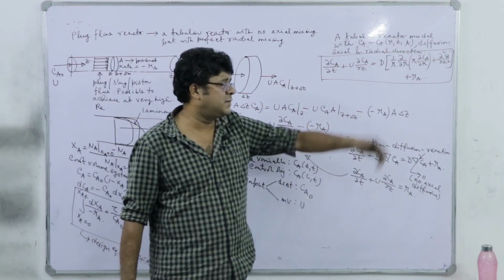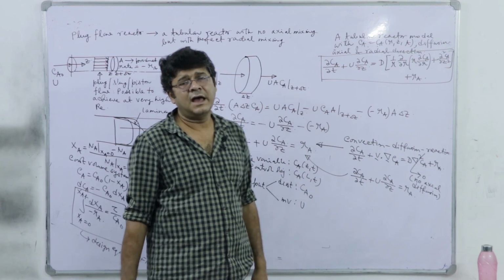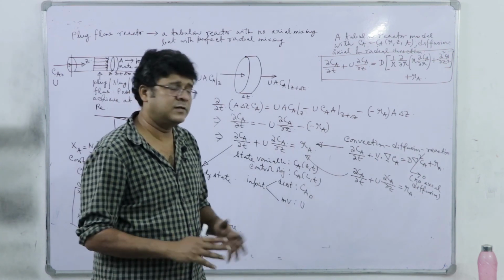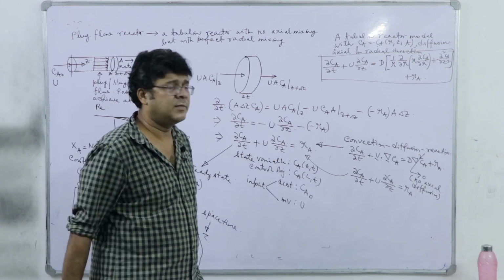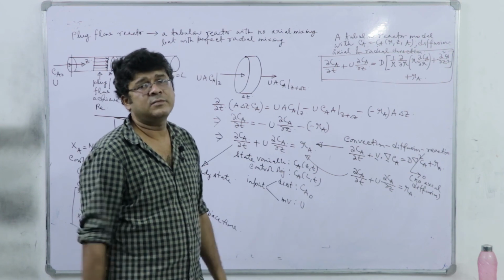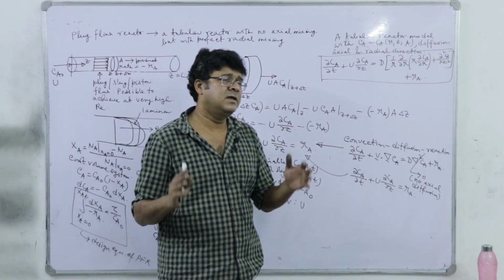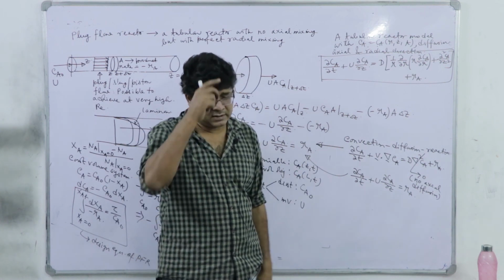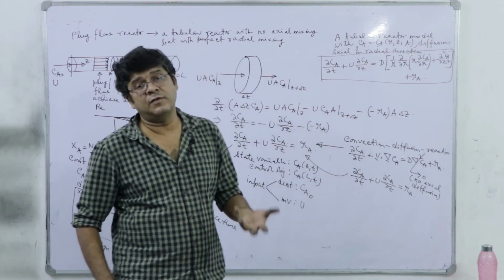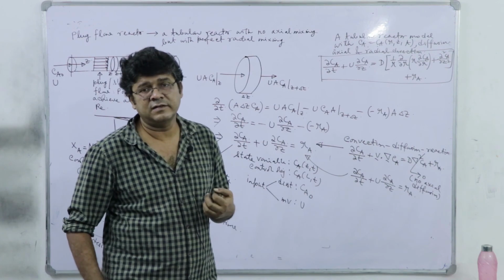Additionally, we have multiple other nonlinear terms throughout the equations, and that restricts the analytical solution of most of these state models. So what we have to do next is linearize them. If it is a single variable, we use the single variable Taylor series, or else we go for multivariable Taylor series expansion, and that we will discuss in the next session. Thank you.